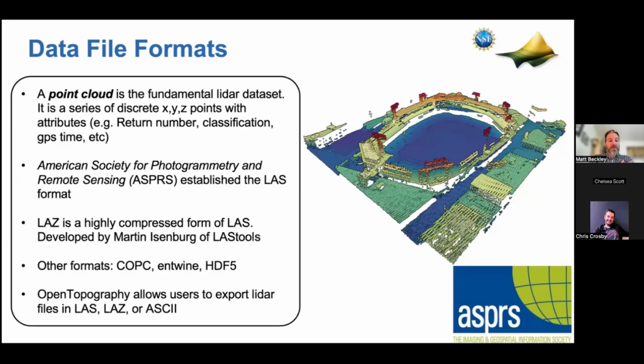But I do want to put a plug in for the LAZ form of this format. LAZ is basically just a highly compressed LAS data format. It was developed by Martin Isenburg, who created the very popular program called LAStools. I've seen LAZ files be like 10% of what an LAS is, so it really compresses quite nicely. This also depends on how the data set is organized. If it's organized properly, it can compress a lot better.